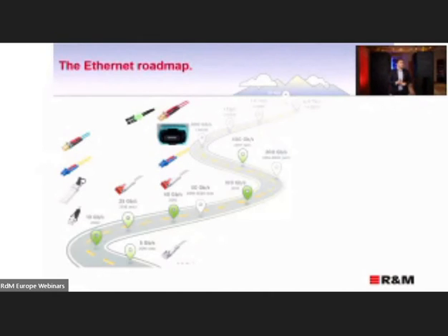Then we have the 40 gigabit application. The application itself is not new, but the new thing is that 40 gigabit is running on copper. Before that, it was possible to run this only on fiber optic, and for the first time, 40 gigabit was implemented thanks to MPO connectivity, which gives many fibers to work simultaneously. But later on, applications to work on just 2 fibers came to life, and today it is also possible for copper.